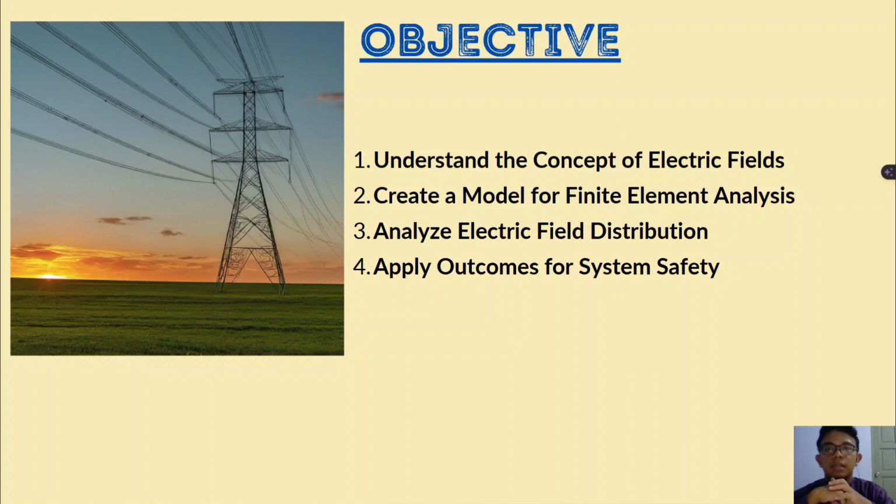Okay, next for objective. First, understand electric fields by using finite element analysis to study electric field in electrostatic problem, focusing on the sphere gap setup. Second, create finite element analysis model by building up a model with material properties, boundary condition, and mesh generation to simulate electric field distribution between electrodes. Third, analyze electric field by studying electric field distribution between grounded sphere gaps to find areas of high electrical stress and risk. Lastly, apply safety measures. Guide action to prevent physical damage and ensure safe, reliable high voltage transmission line operation.